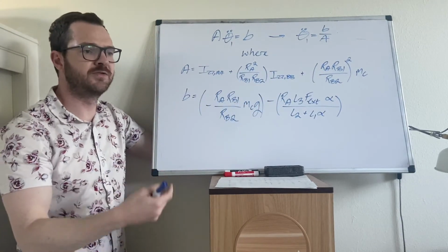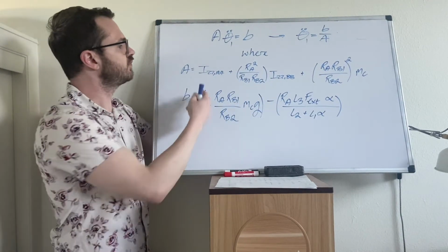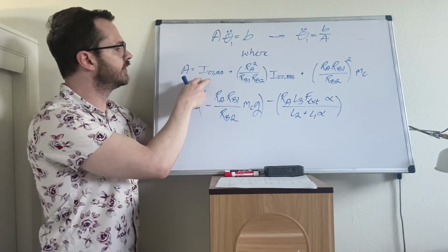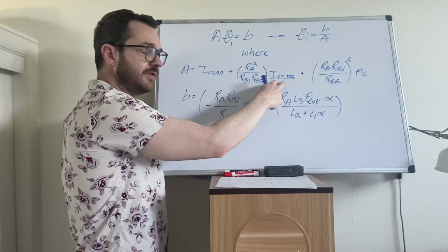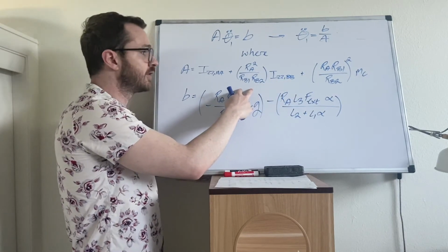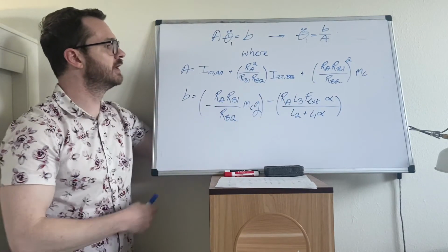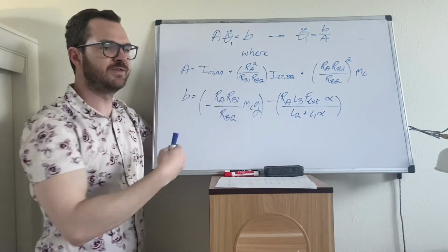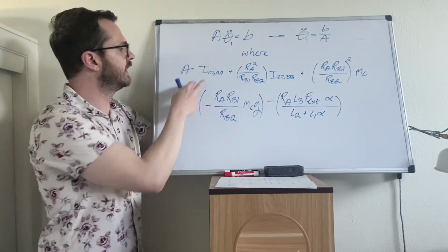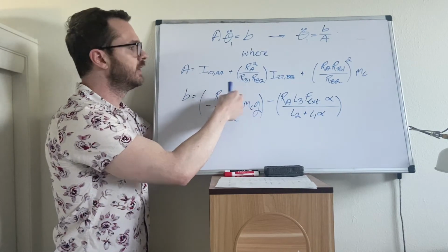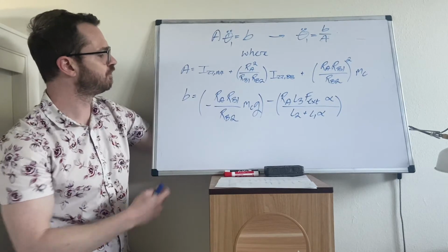So that is your resistance to change. And notice that it's all positive. So the inertia of disk A, the inertia of disk B modified by the gear ratio, and also the mass of the block modified by the gear ratio. All of these things are resisting change in their current state. So they all add together through some weighting system that comes out through the constraints.